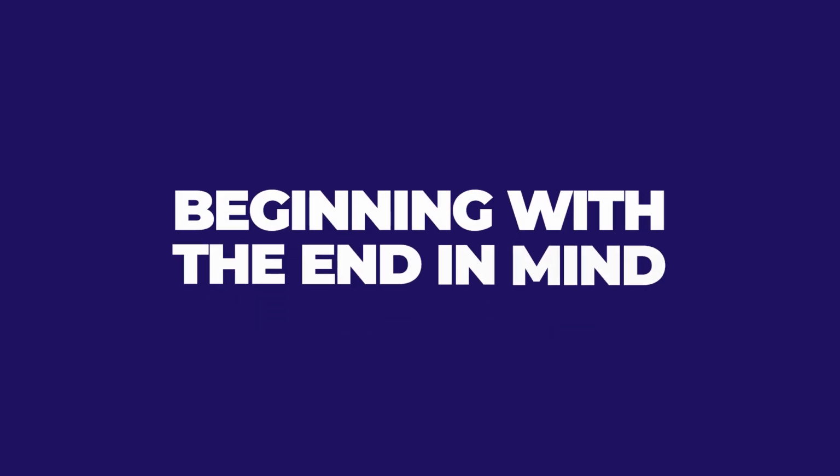You take that back and you say, how am I going to sequence the exteriors? Then you run that back. How will I have to sequence the superstructure? Then the foundations, then everything from the start. You always begin your sequencing from the beginning with the end in mind. Here's what I don't want. I don't want you to end up painting yourself into a corner.